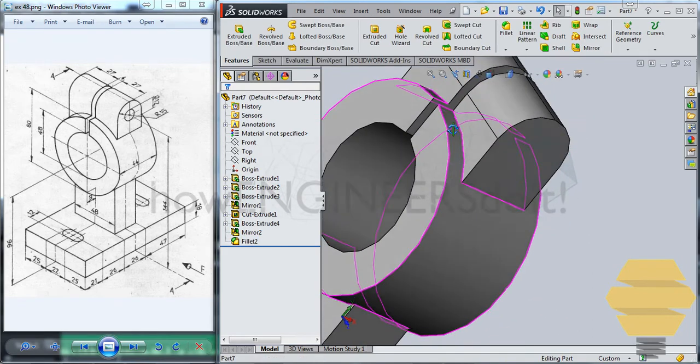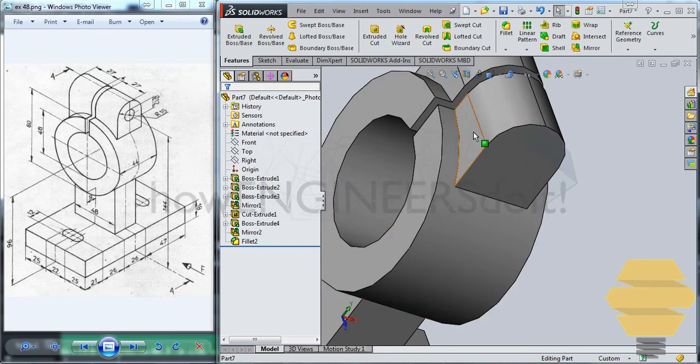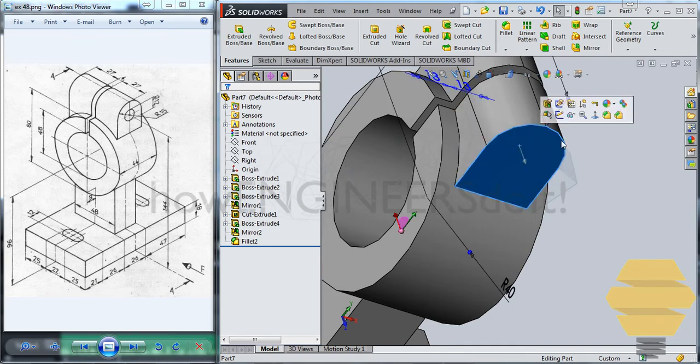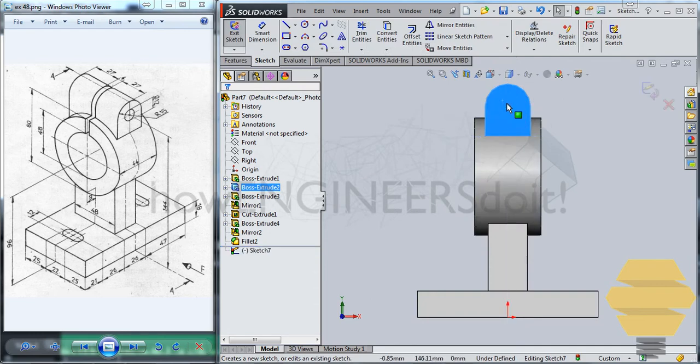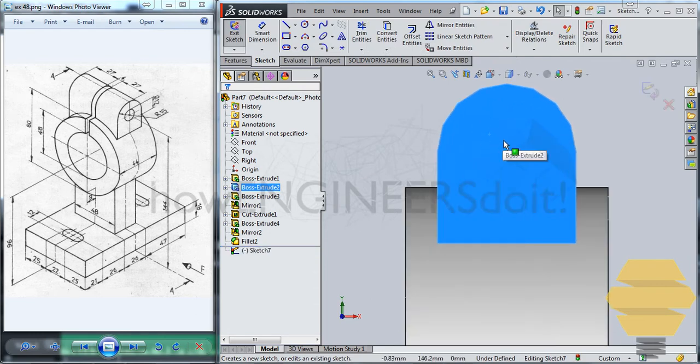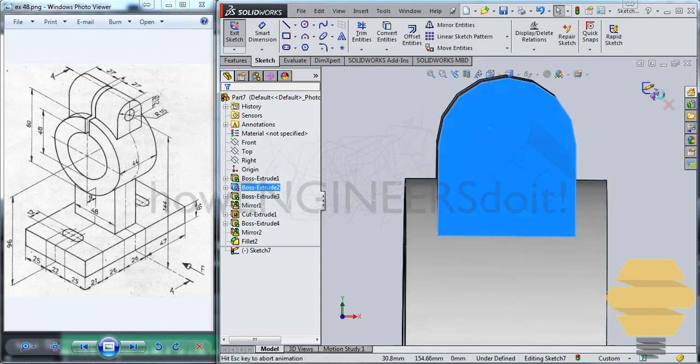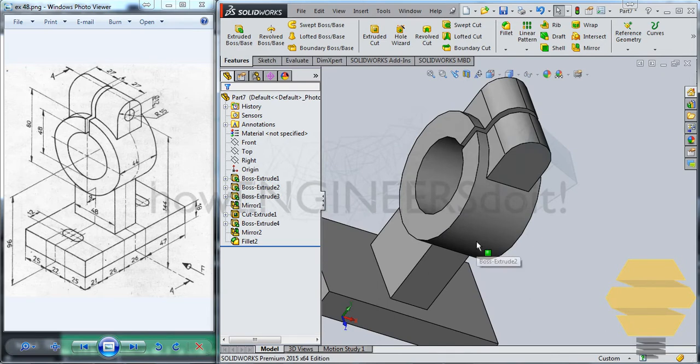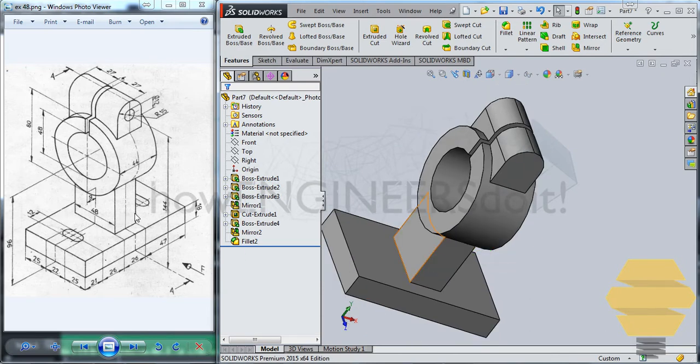So now I'll explain to you the reason why I've done that. The way that I found that was wrong is because when I was about to create a circle over here and create a hole, I found that this curvature was not smooth. So then I found that the thickness over here and the thickness over here is not equal.